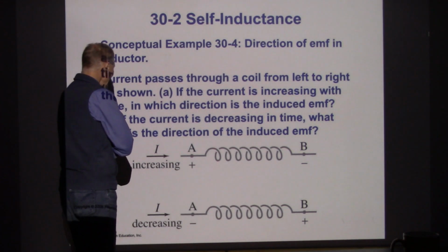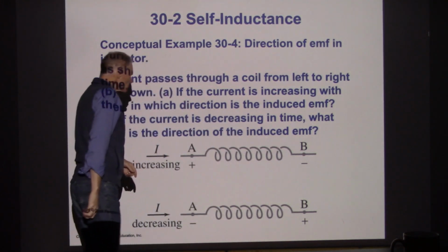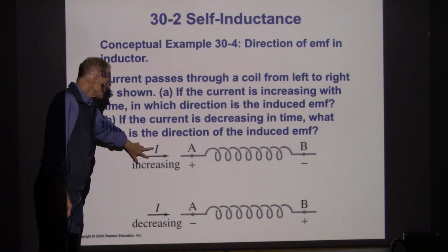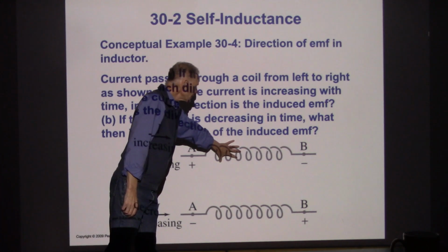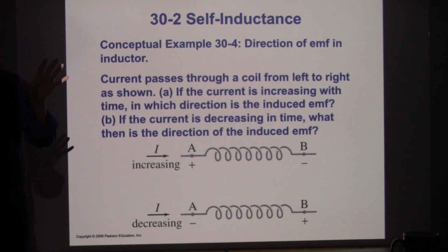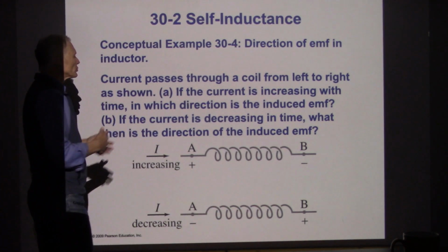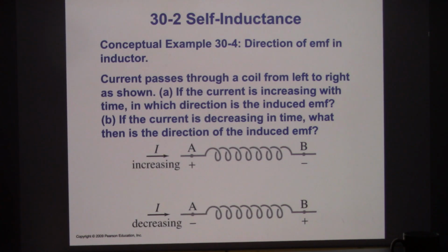And what happens is, if we have a current going through an inductor, and the current begins to increase, if we have a di/dt, then the electric fields that are set up within an inductor push on everybody else and say, no, wait a minute, let's slow down, let's not raise the current too fast. And so inductors actually moderate changes of current.